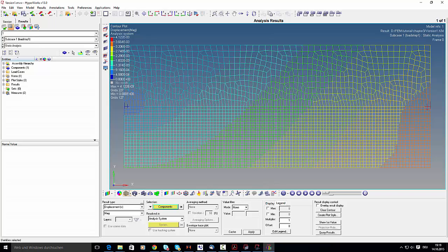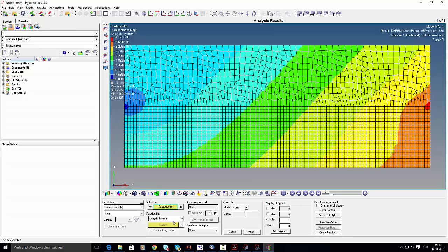I'll show you the mesh. The mesh in the upper part is coarser than the mesh in the lower part, so this has a higher restriction against forces. So it's always with coarser meshes, and the finer meshes reacting better, or like in more accurate, and so this is stiffer than this side. So that's the reason we're going upwards. I will also show you the element stresses.